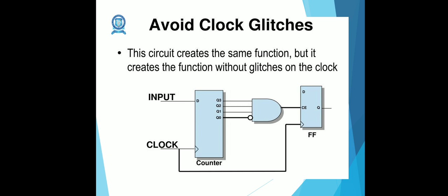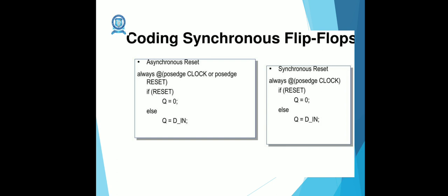Clock glitching is one of the oldest and most widely used methods of fault injection. It requires inserting short glitches into the device clock, which causes timing violations inside the device. Glitches can also be removed by introducing a negative edge triggered or low level sensitive latch at the output of the clock. This makes sure that any glitch in the circuit signal will not be visible to the gated clock output.